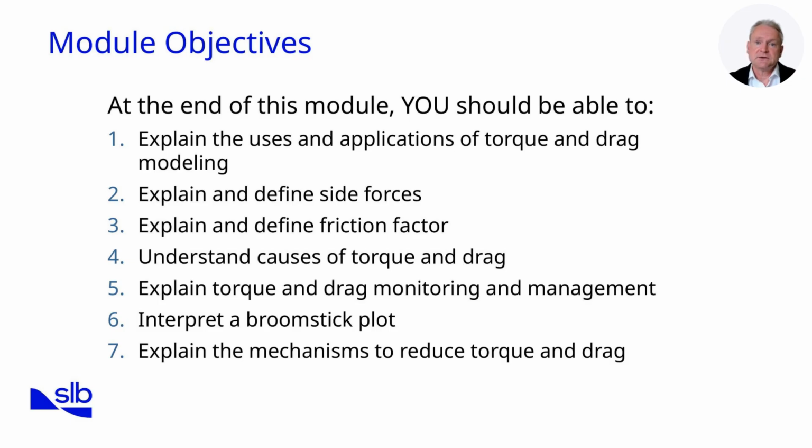Another key objective is to understand the causes of torque and drag. Recognizing these causes is essential for anticipating drilling challenges, particularly in deviated and extended reach wells. Additionally, we will examine torque and drag monitoring and management. This includes how to interpret field measurements and use them to diagnose potential hole problems before they escalate. Finally, we will introduce the broomstick plot. This is a simple yet powerful diagnostic tool for visualizing torque and drag, as well as for comparing actual field performance with predicted values.